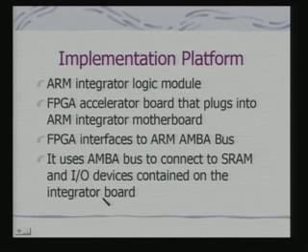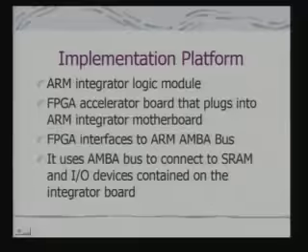The integrator board is basically your hardcore host CPU, and this accelerator board is the basic hardware framework on which you will be implementing the required function. This accelerator makes use of the same AMBA bus to communicate with the processor, as well as to make use of the memory and IO devices.